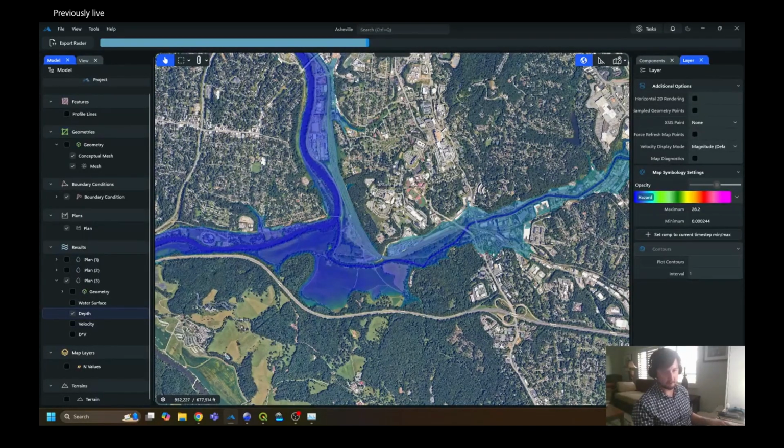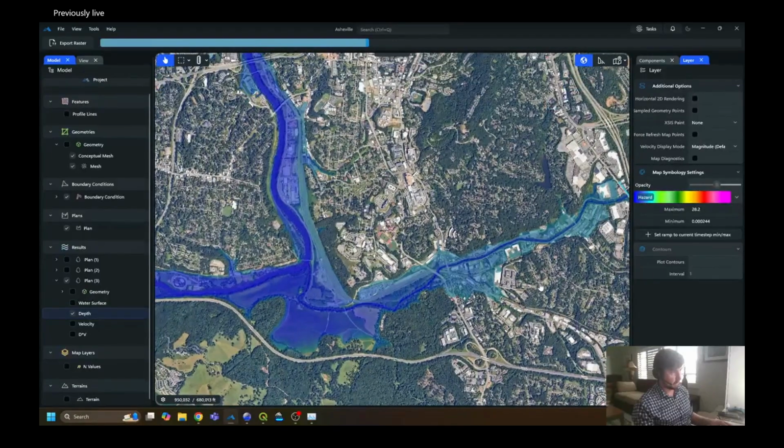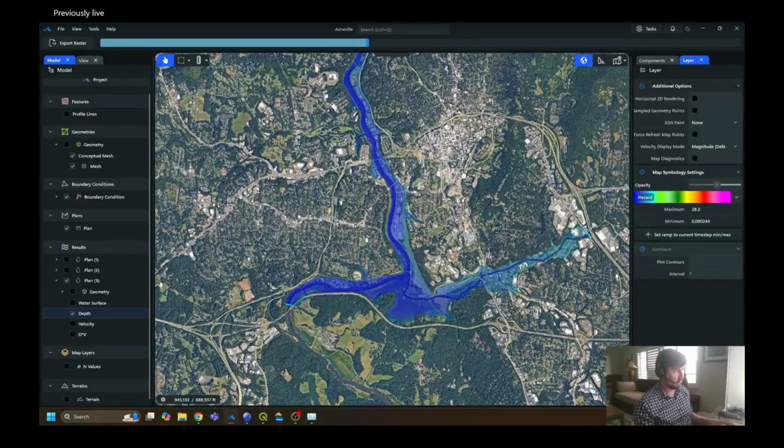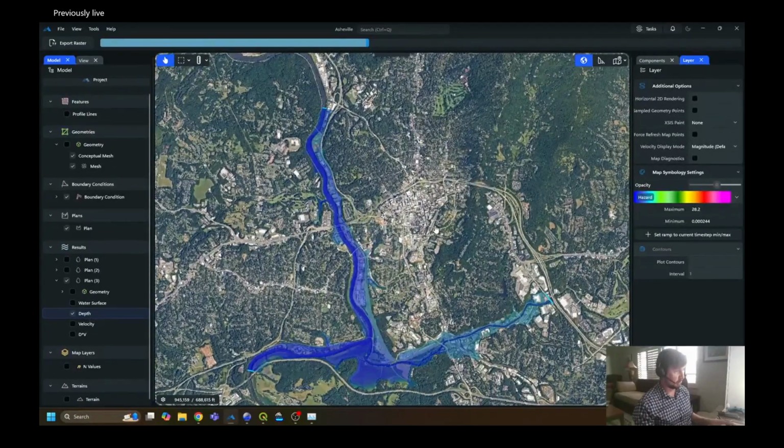I would be really interested to hear feedback from folks that have tried out that new tool. One of the workflows I imagine is going to be really useful is you build the 1D elements in SWMM. And it would be really nice to have just a purely 1D model. You get that to run real nice. And then if you want to throw in the HEC-RAS 2D workflow to that, then you can actually compare and have those two models be separate but working together.